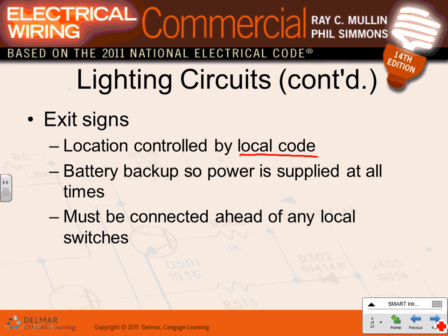Exit signs. Do we circuit them? Yes. Do we switch them? No. What voltage can I get them? You can get them from 120 all the way to probably 480 volts. And they have a backup power, guys, always, right? Battery backup power, and they're connected always.